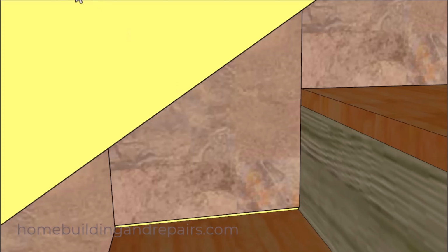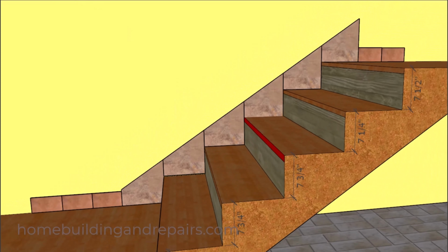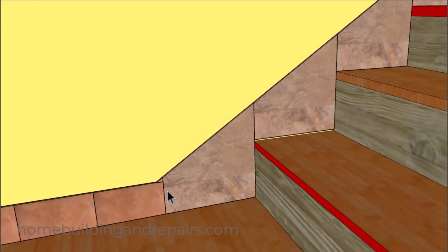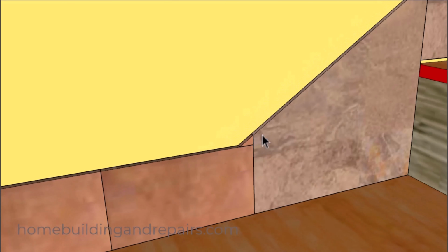Taking us back to my original reason why I cut each one of the tiles to fit the length of the treads and then created a straight line here. And if I want the tiles on the bottom to line up, I could always cut a little piece here or use another one of these tiles to get over to here and shape the top of it accordingly.